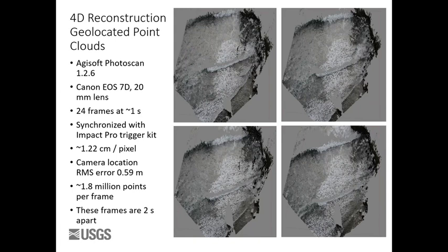So there's a way now to synchronize cameras using the GPS signal, and you have to have them very synchronous, but you can take part of the GPS signal. So you could have 3 drones all flying and take pictures simultaneously of the water surface, which is huge for all of us, because you've got these pictures. You can measure the wave height, you can measure the wave angle, you can measure the wave speed because you've got time, you can measure the amount of braking.